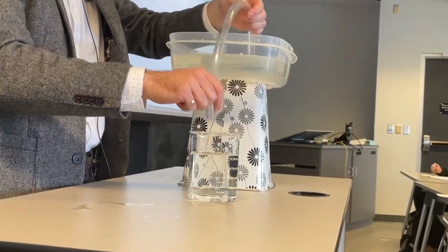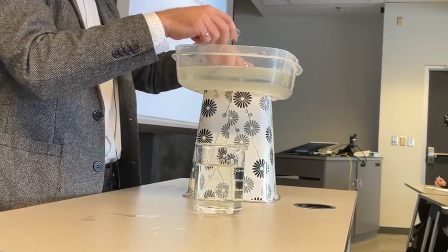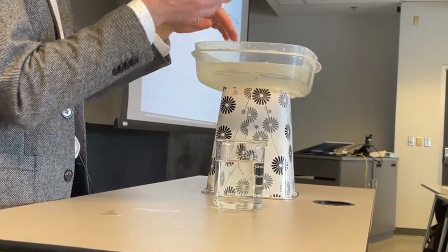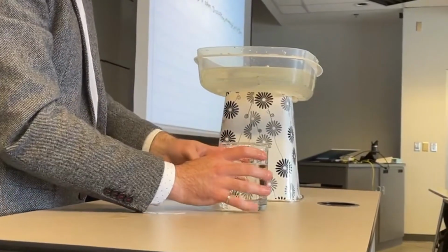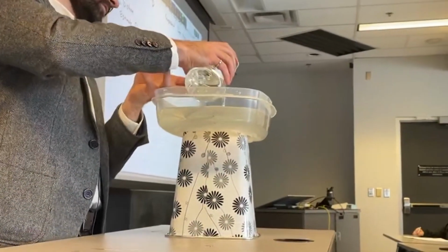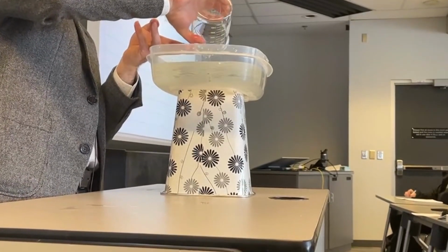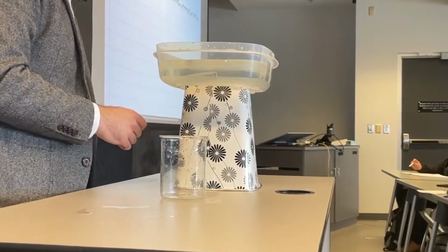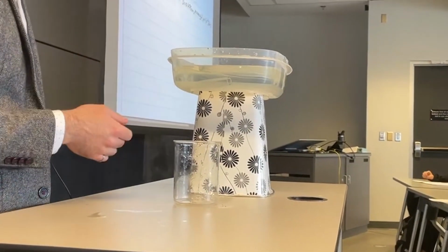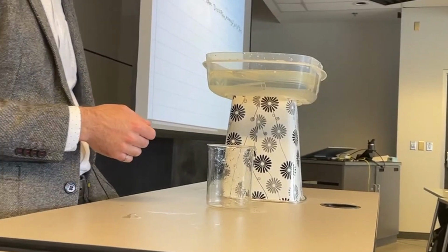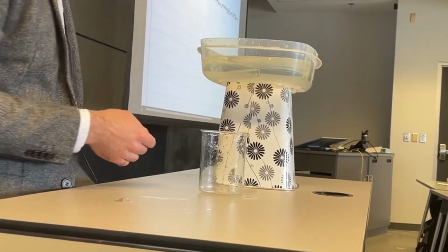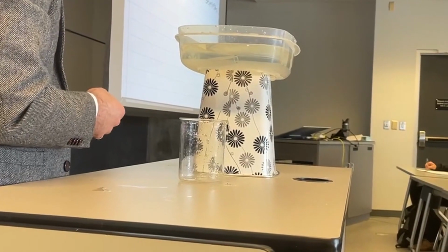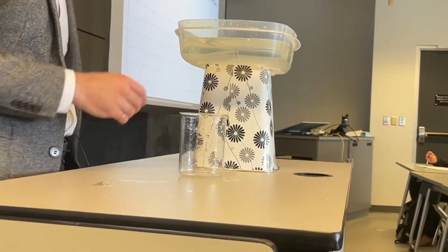The driving force behind this fluid's motion is the hydrostatic pressure difference here. There's no pumps, there's no anything. We're just using gravity to drive this flow. The only difference between the 2 diameters is the differing frictional losses in the system. You might have seen a higher diameter pipe has lower pressure losses, so that's why. Okay, so I'm going to set this problem up and then we're going to do some analysis here. The math will get a little bit ugly, but the end demo will help us motivate this.